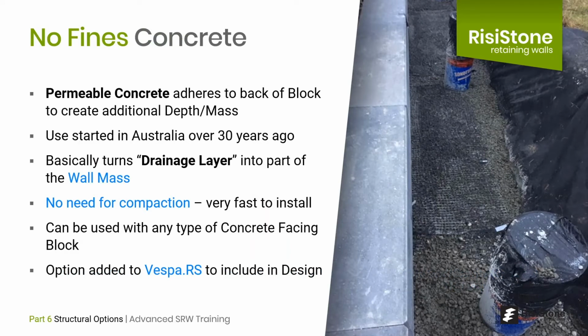As mentioned, we will take a closer look at no-fines concrete, the first of the newer gravity options discussed. No-fines concrete is basically exactly what the name indicates, a concrete mix with little or no fine content, primarily made up of one size of larger aggregate, water, and cement. It was originally developed in Australia over 30 years ago. Because there are no fines in the concrete, it has large voids present between the aggregate, which allows water to flow through, making it permeable.